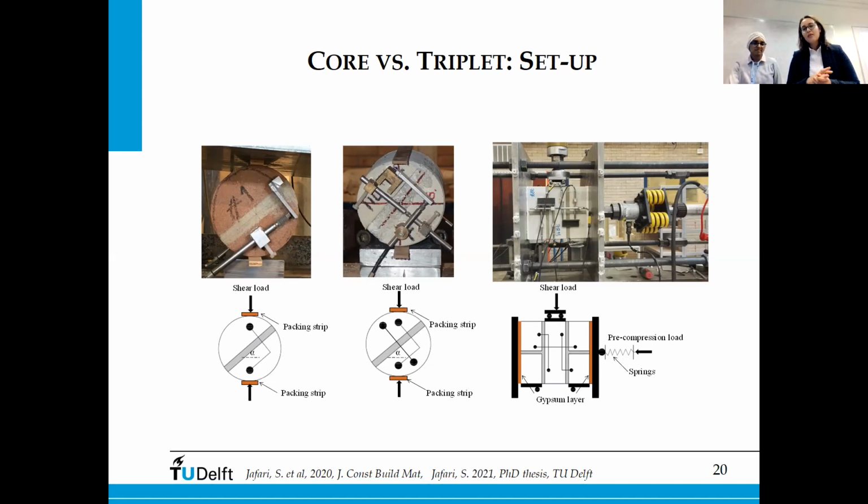The thing is, I chose this method because of trying to have limited input parameters. I worked on this method in the past for concrete, and it was quite okay for what we could do. But for masonry, the friction part is of much relevance, and there are not many studies that include this. The main problem with this model is that we need to work with a crack embedded in an isotropic matrix, which is already there.